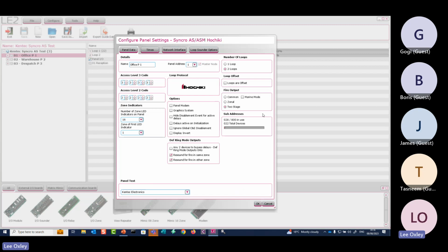Okay, so that is just a really easy way of creating a cause and effect while all your sounders are in default ring mode, one out, all out. An easy way of creating a quick cause and effect without writing a cause and effect line out. If you're doing things by cause and effect, by default, they're just all in common, or one out, all out, basically.